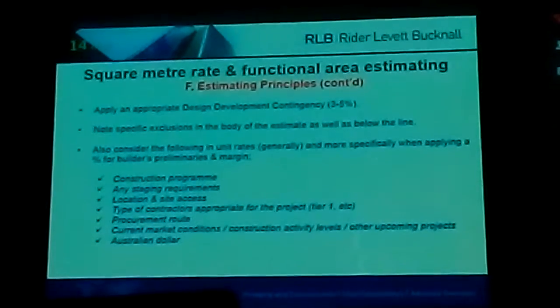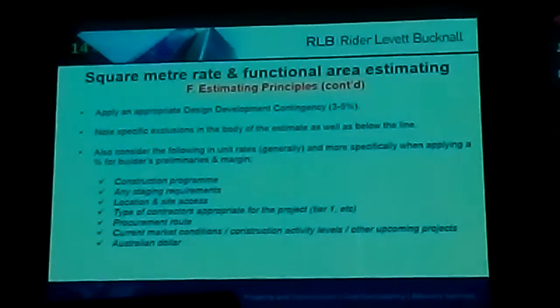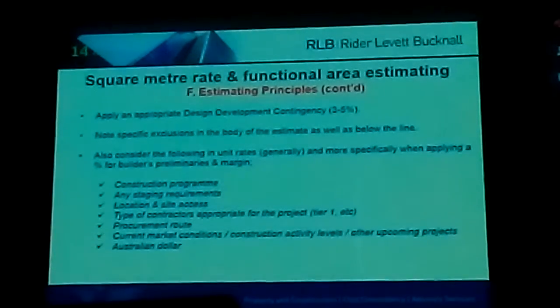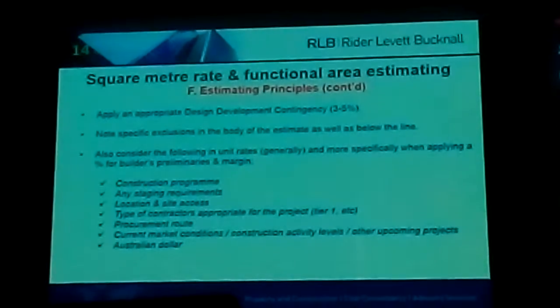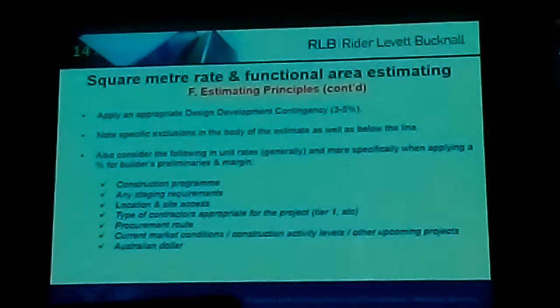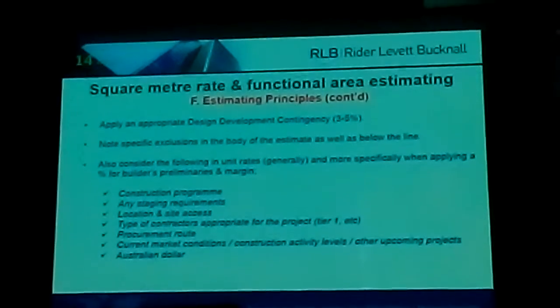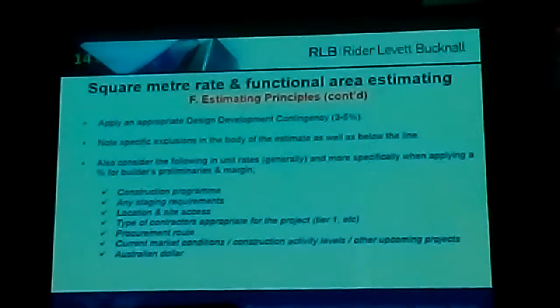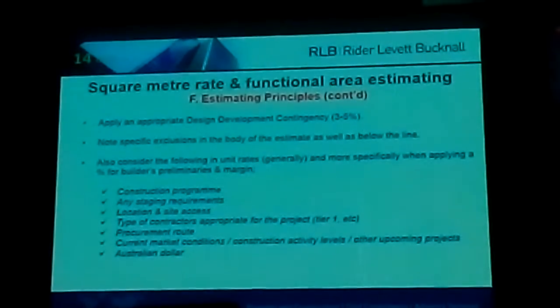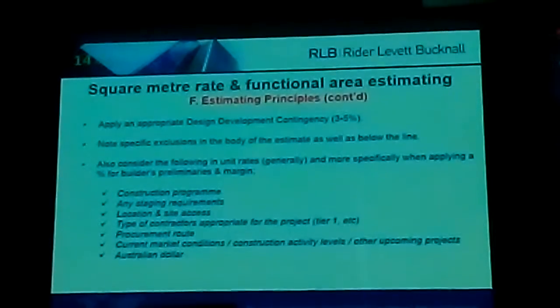Also consider the following in unit rates, and more specifically when applying the percentage for builders' prelims and margin: construction program, staging requirements, location and site access, type of contractors appropriate for the project, procurement route, current market conditions and activities, and the Australian dollar.